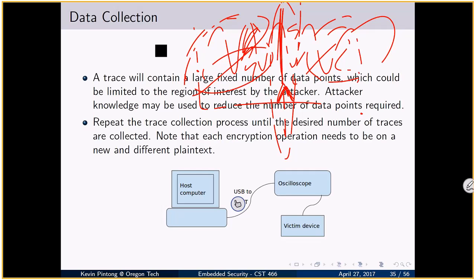So we take multiple samples, right? Capital D number of traces. Each trace, the data changes randomly, right? Each time the encryption occurs, the data points change randomly. So the data points change randomly each time you run the encryption. By using different values each time, on average, it's going to produce that profile.